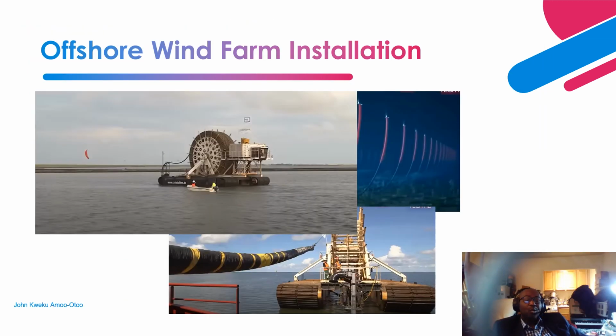Definitely, we need cables: AC cable installation, export cable, and inter-array cable. Okay, so typical inter-array cables will be 33 kV or 66 kV before it goes to a collection point. Right? Okay, so these are the cables, how the cable installation is done, and we also have the DC cables.